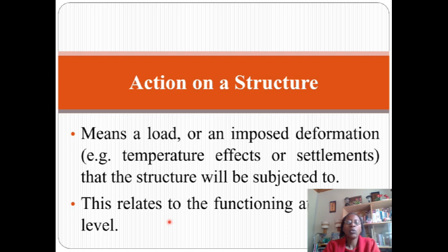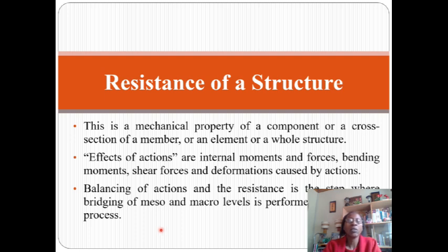Very important to note, action as we know it is a load or an imposed deformation, and it relates to the functioning at the macro level. The resistance of a structure is very important, a mechanical property of a component or cross-section or element or even the whole structure. The effects of actions are the internal moments and forces, as we know, and in the design, what we do is to first come up with the balancing of actions and the resistance.